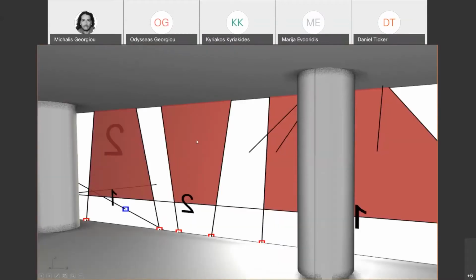So the generation of horizontal sections in each of the building's discrete planes, which were the horizontal slabs, allowed for a traditional setting out process. And also the connection between these points in a single dimension, or on a straight element, created a variant of a conventional setting out method that defined the shell's geometry.